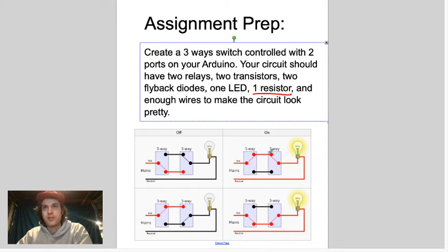Okay, if they're both on the same lead, which we can't really see because that's in our walls, that's why you can go up to the top of the stairs and flip, and then come down and flip, and then go back up and flip. And so that's why you can have the light bulb be on with these switches in different configurations, which is kind of cool. You could have the light bulb on and this switch facing up, or you could have the light bulb on and this switch facing down. It's pretty miraculous. Yeah, so let's go ahead and take a look at Tinkercad.